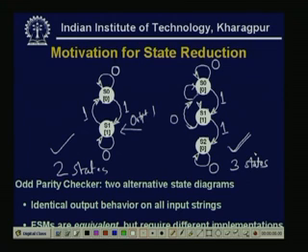So which one will we be choosing? See, now the implementation will be different, because here there are 2 states, so we need only one flip flop, for the 0 and 1 state. Here it is 3 states, so at least we need 2 flip flops. If we do the state encoding, then 00, 01, 10 or 11, any one of these we will be taking.